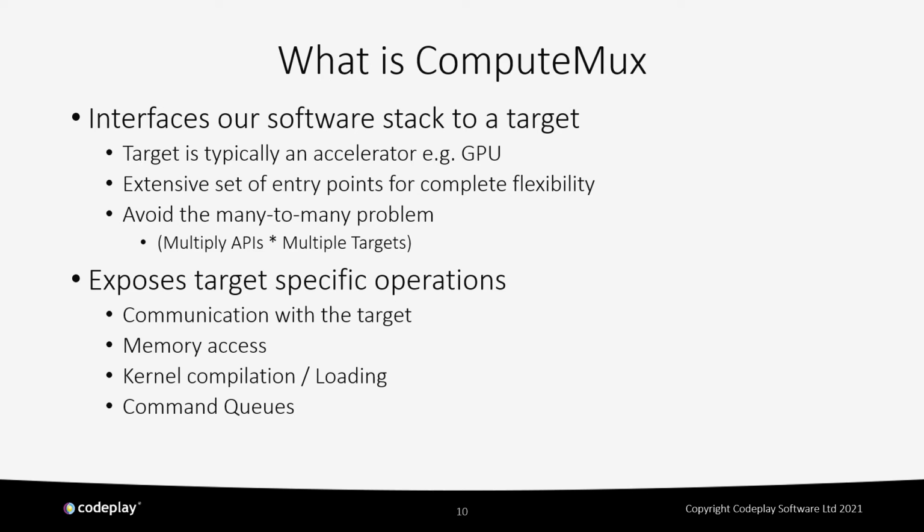So Compute Mux brokers all of the memory access to a device. So for global memory, for instance, it will handle things like allocation, reading buffers, writing and filling them. It also abstracts away kernel operations, such as the compilation of kernels for programmable units and the dispatching of kernels, which might be for programmable units or even non-programmable units. Compute Mux also operates on a command queue principle. So a queue of commands is constructed elsewhere, higher up in the stack, and this is then passed down to Compute Mux, which will then dispatch those operations and hand them over to the device to be executed or actioned.